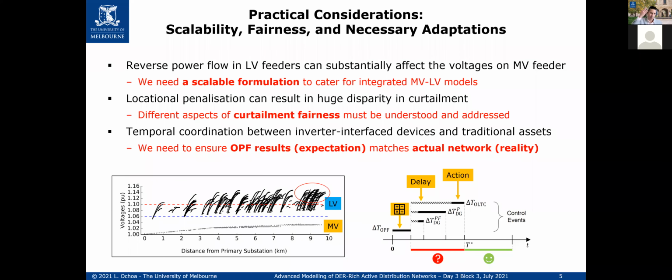You have a remote connection, so if you need to control them, you can, but they are always operating locally. So they are checking their voltages. For instance, an on-load changer is checking a voltage at the bus bar of the primary sub, or even if it is a remote voltage, the decision is all local, right? And the process is all local.